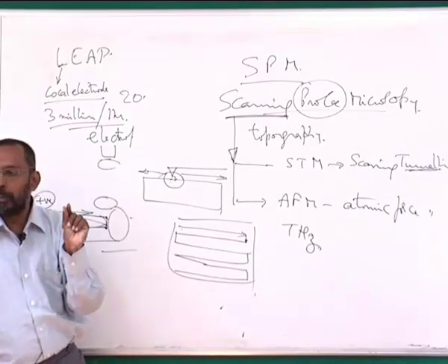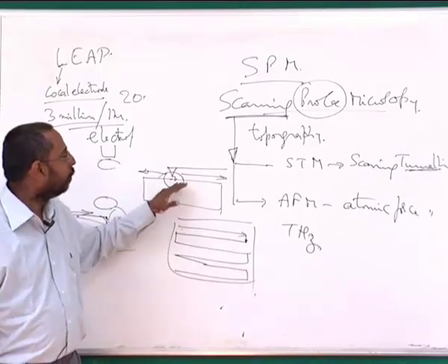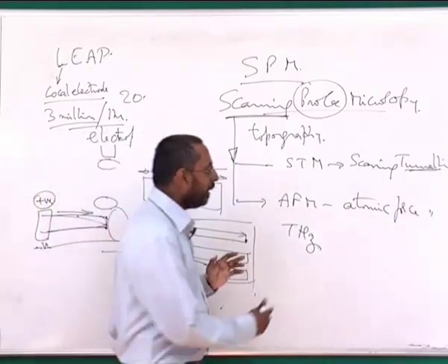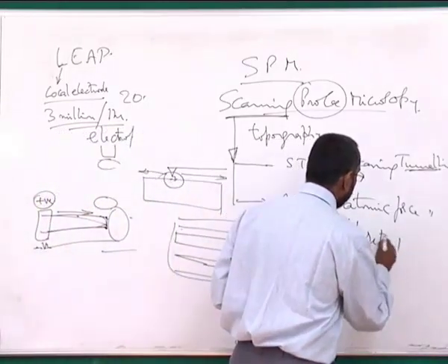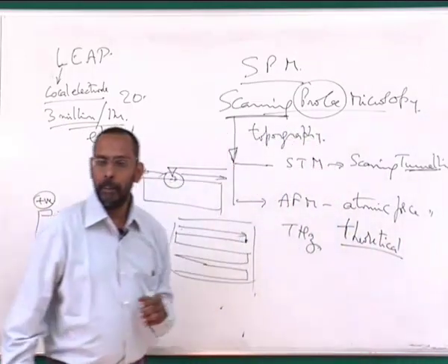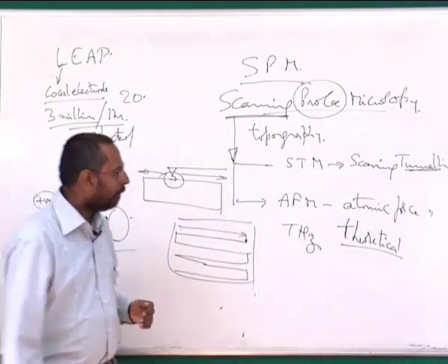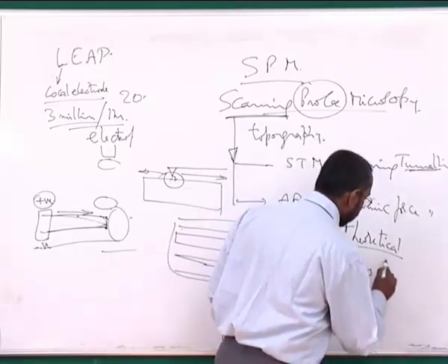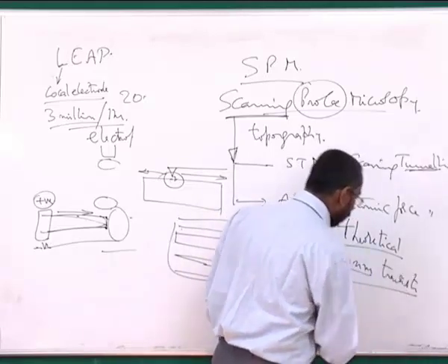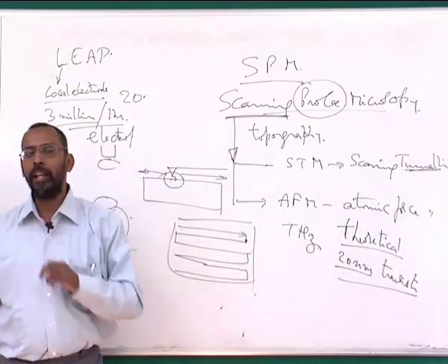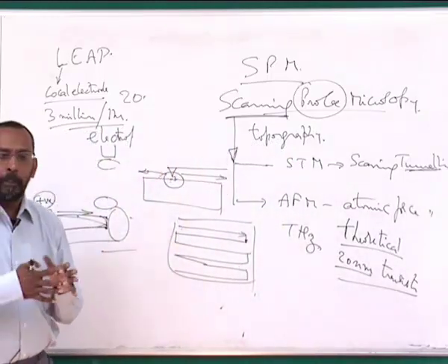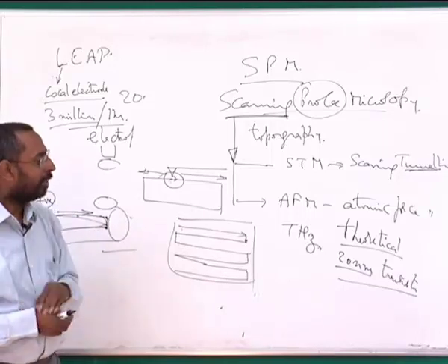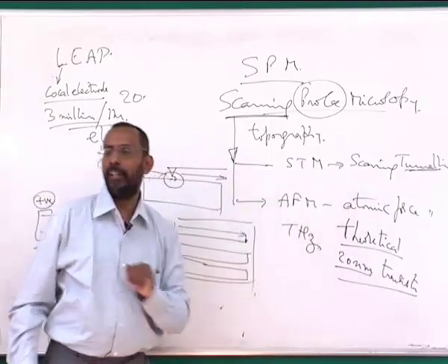So because the distance between the two is too small, you reach such a limit of tunneling, and people say that is a theoretical limit to which you can reach. So nowadays people believe that with the 20 nanometer transistor that is already available, if you go further down to 10 or below 10 and put a large number of them into a smaller area, you would see that you are already reaching that limit.